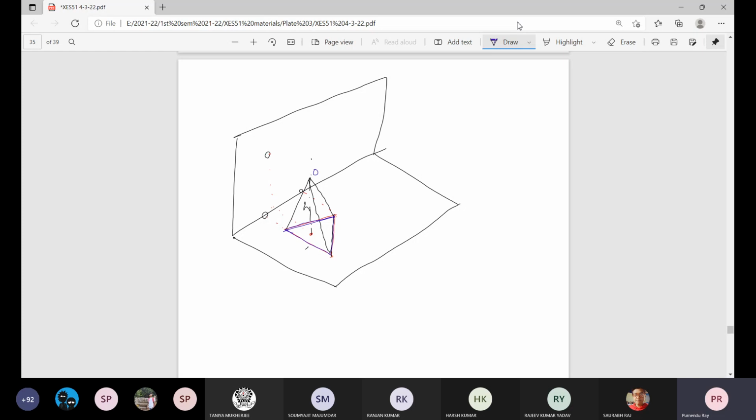If it is O, these locations are A, B and C. Now AB is perpendicular to VP, so AB is perpendicular to GL. Project it here. This will be elevation AB. And project the point on the ground line. C is on HP, so this will be elevation C. Now the height of the topmost point O, that height H is there.